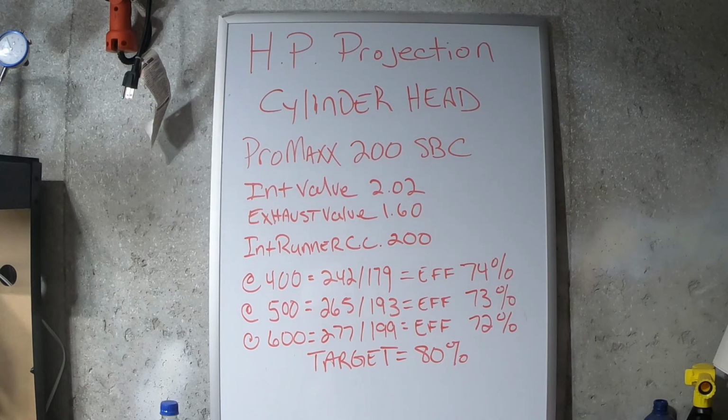When you select cylinder heads, do not get them unless you know how they flow on a flow bench. And you may have to do a lot of digging, like I did. But you can find it, or ask your machine shop. They may have experience with doing flow benching for other customers, and they may have data sets on file for specific types of cylinder heads.